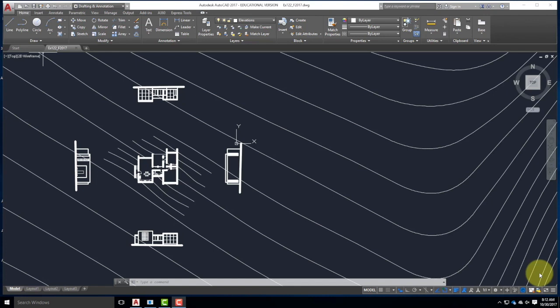And so I'm going to walk through today key concepts in AutoCAD, and it's called Modelspace and Paperspace. Modelspace essentially is what we've been working in. It's the space with the black background. It's where you draw everything full size. So you're drawing a floor plan and you have a room and it's 12 feet, you draw it at 12 feet. Paperspace, on the other hand, is like a sheet of paper. And it's now, how does your drawing fit on that piece of paper?